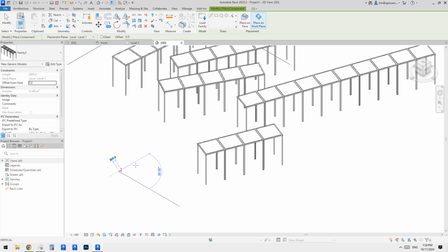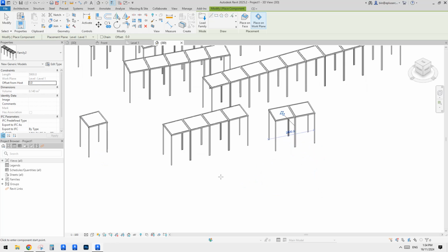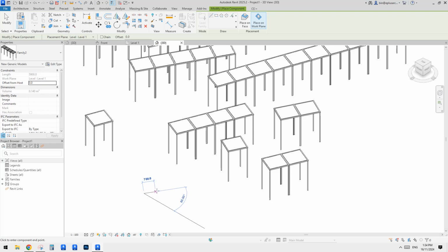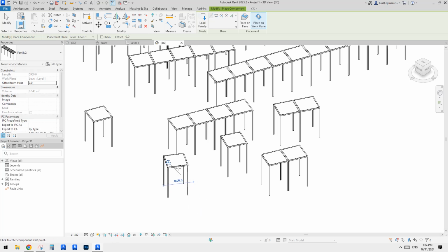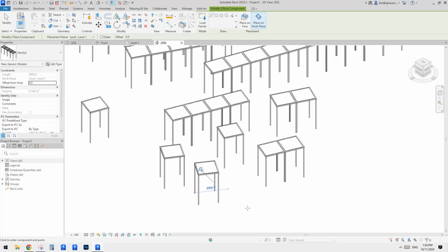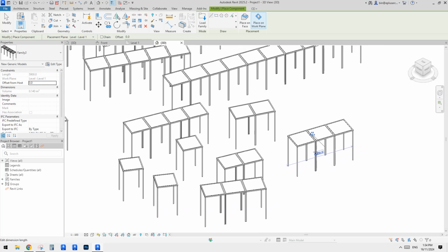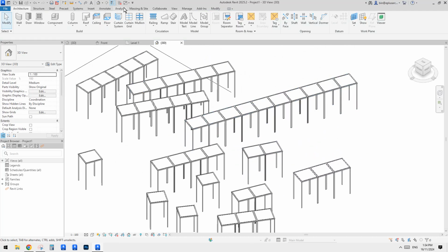line is. And the good thing about this in Revit 2025 is, you can see if this line is less than the W, the array becomes 0, so there's nothing. And if it's longer than the W, there's 1, right? So previously the array would break if we had less than 2. Okay, so this is a line based family, right?